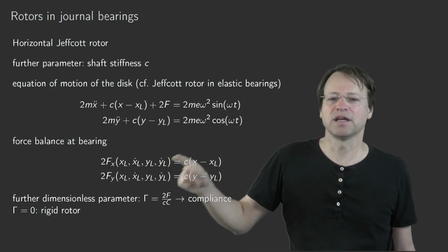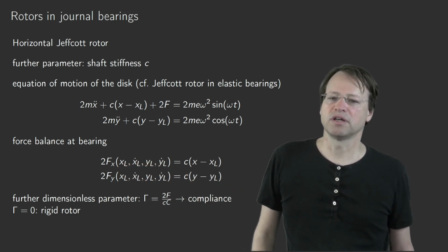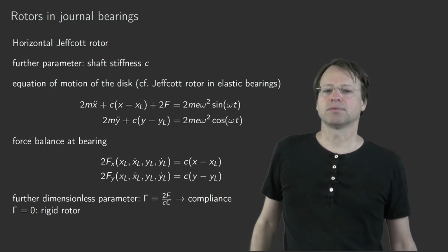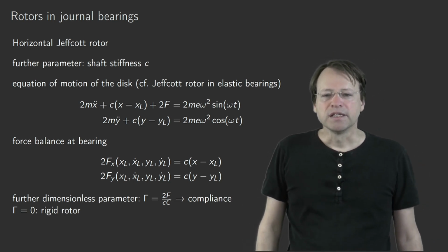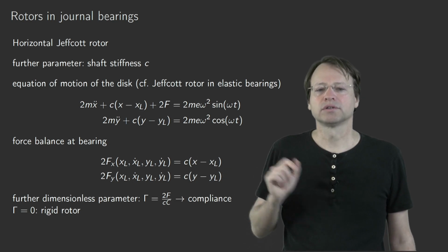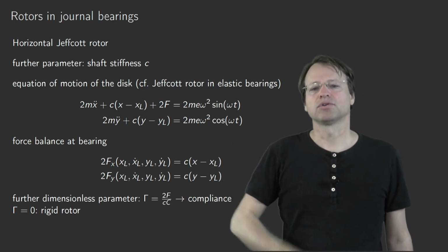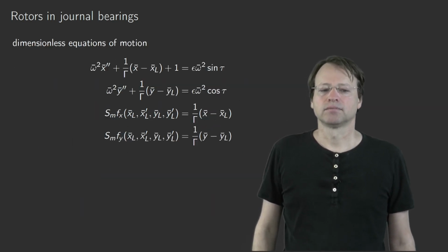They are well hidden, but they are present. Namely, we have the stiffness and damping coefficients on the left-hand side, but no inertia parts, as we consider just a quasi-static force equilibrium. That means due to the first order derivatives, we add two more orders to the characteristic polynomial. So the characteristic polynomial for the Jeffcott rotor will be of order 6.